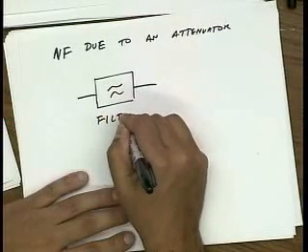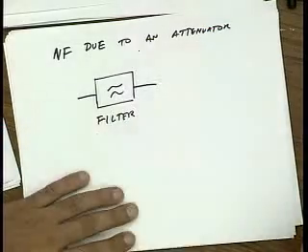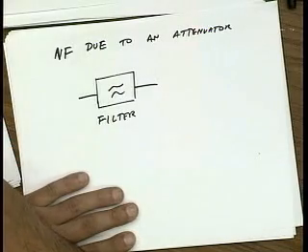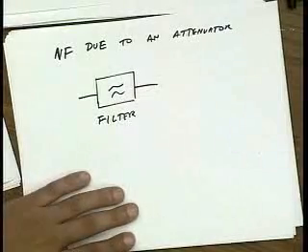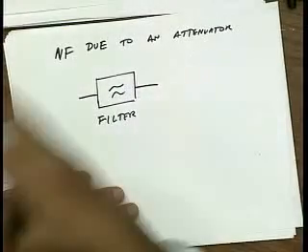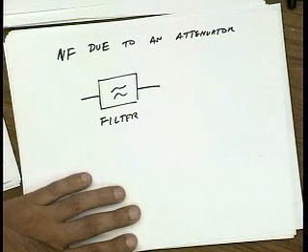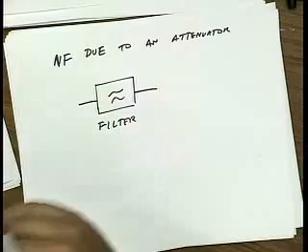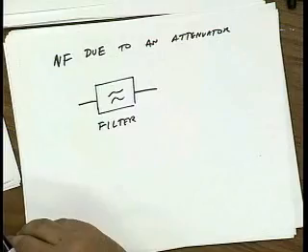All communication systems, or nearly all communication systems, need a filter to reject all the out-of-band interferers, right? You looked at homework number 4, the AM radio station, and you looked at just how many interferers you had just in the AM band. Now imagine that there was no filtering at all, so you picked up broadband signals all over. You can imagine that many combinations of signals, 2 tones, 3 tones, 5 tones, 110 tones, could combine in some nasty way to mess up your amplifier. So the simple solution is just put a filter to get rid of all those out-of-band interferers.